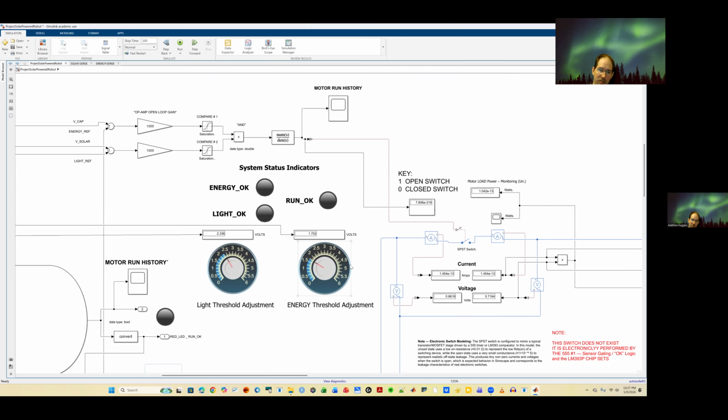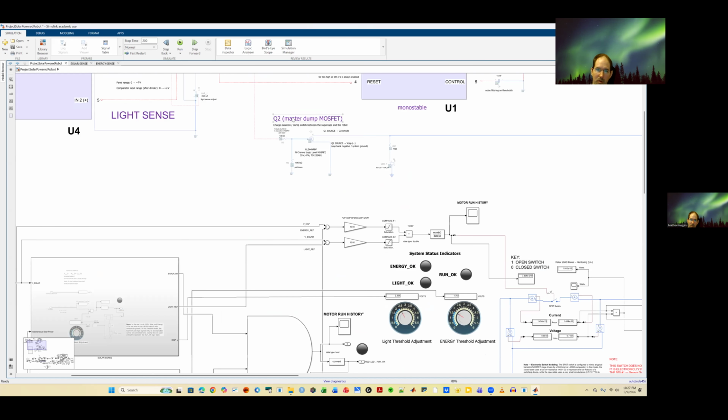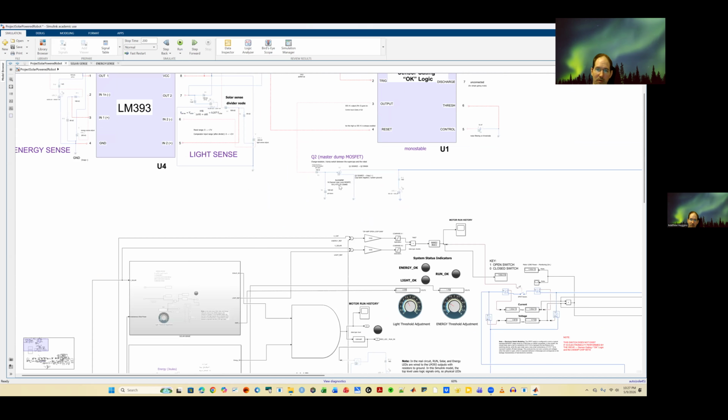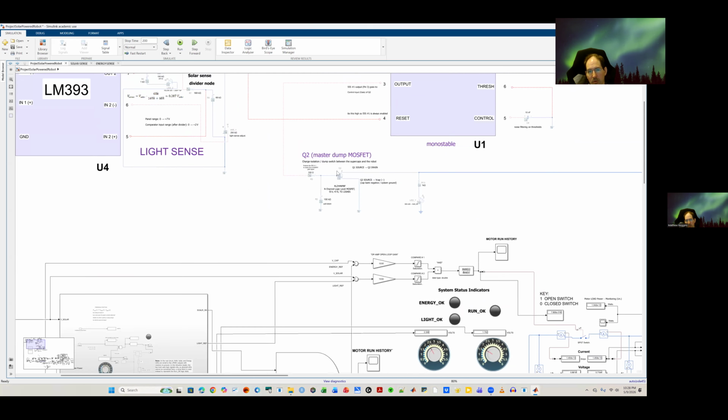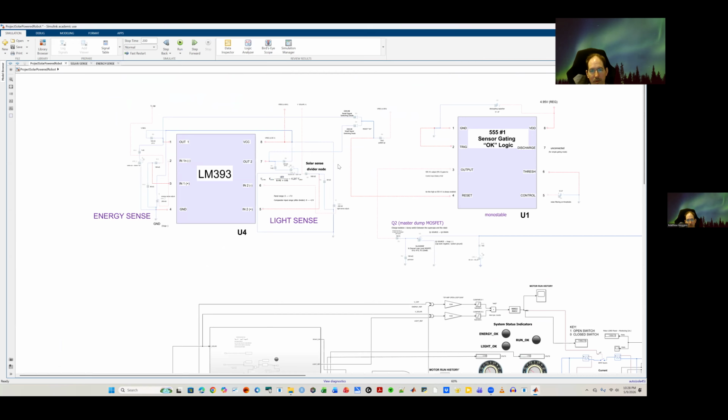connected, and the capacitor bank has a chance to charge, so it can be used again. Without this, all the power just keeps bleeding off of the motor, and nothing ever happens. So that's why it is critical that the second MOSFET had to be added here, and I couldn't just use one for pulse width modulation. I needed a second one controlling like a clamp, shutting and opening when the motors receive and when they don't receive power at all, or current, basically in volts, from the pulse width modulation controlling volts.